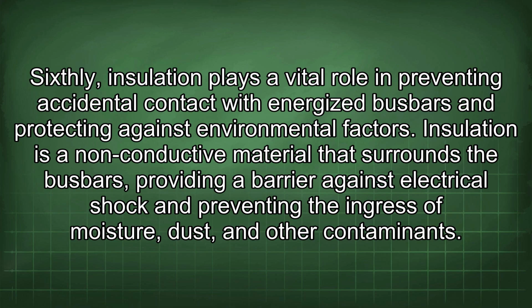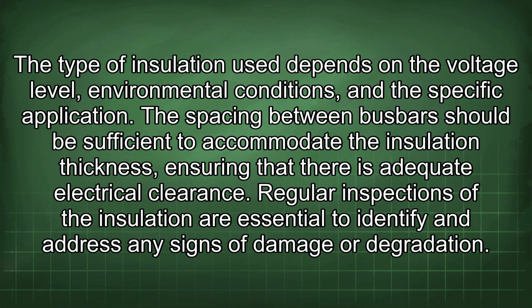Insulation is a non-conductive material that surrounds the busbars, providing a barrier against electrical shock and preventing the ingress of moisture, dust, and other contaminants. The type of insulation used depends on the voltage level, environmental conditions, and the specific application. The spacing between busbars should be sufficient to accommodate the insulation thickness, ensuring that there is adequate electrical clearance. Regular inspections of the insulation are essential to identify and address any signs of damage or degradation.